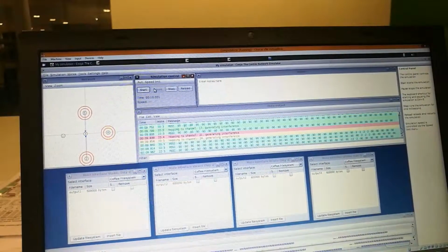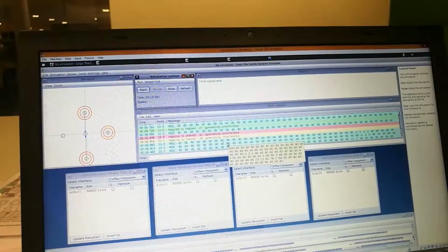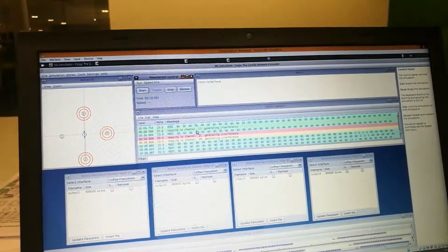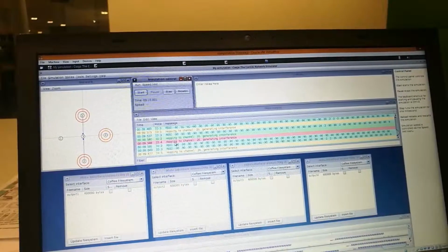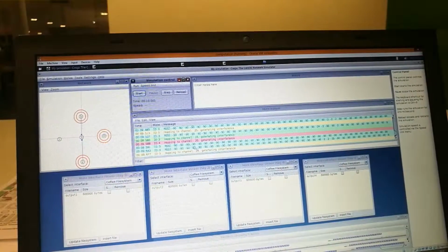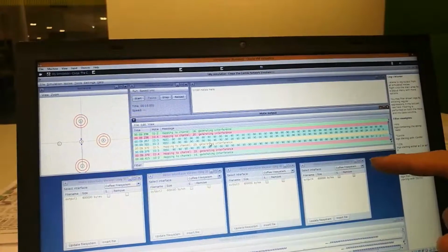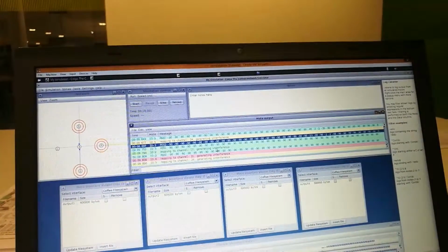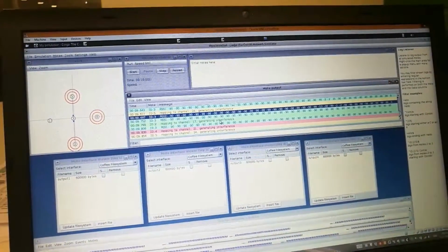From the mote output, we can see the printed RSSI value. -100 means there is no interference in this channel. Other numbers above -90 are the signal power received in this channel. We can also see channel hopping from our mote output. Take node 4 as an example. We can see it jumps from 20 to 22, and then it jumps to 20 and 21. By this method, we can use 4 interferer nodes to generate 16 channels interference. Then we start again.